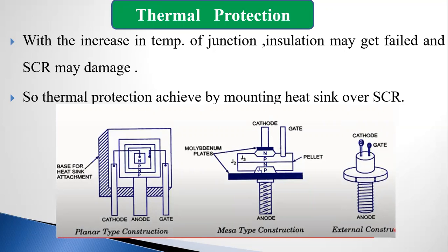As you have observed in various electronic equipment in our laboratory, like the CRO and various devices, they are also protected by a heat sink. So this is mandatory for electronic devices, semiconductor devices, to provide protection from high temperature; we provide the heat sink. In that figure, you can see how to provide the heat sink in the SCR. We can say that for the thyristor in planar type construction, this is the base for heat sink attachment. In this area, we can attach the heat sink.